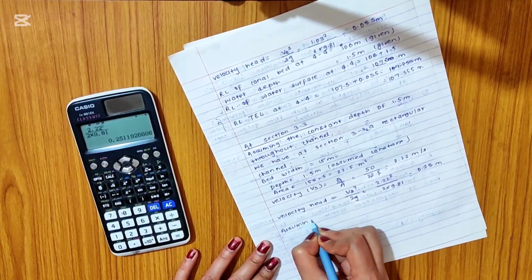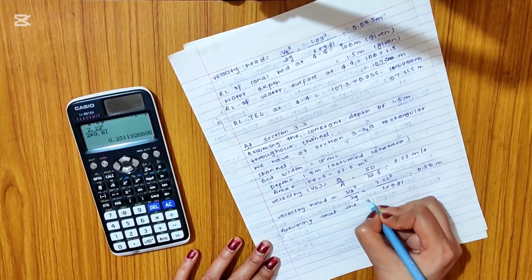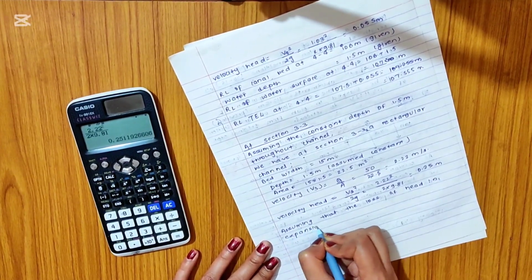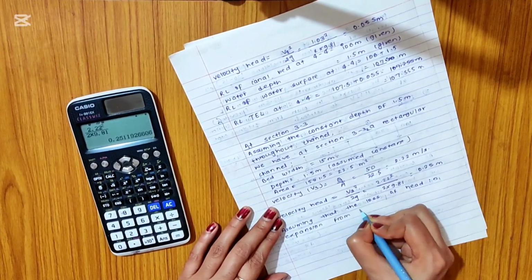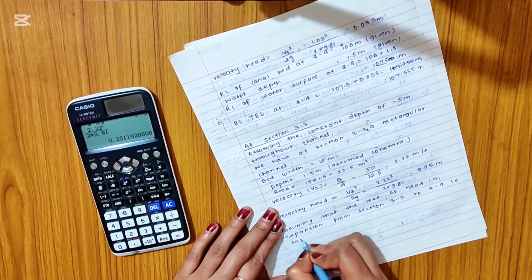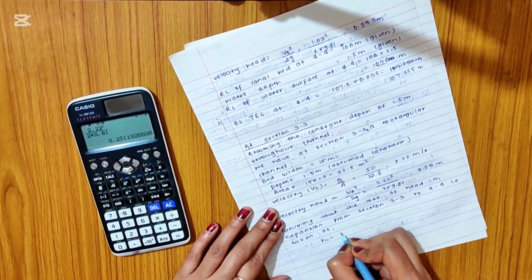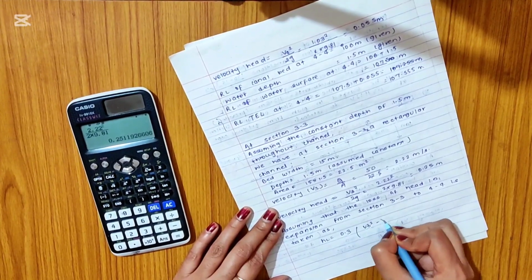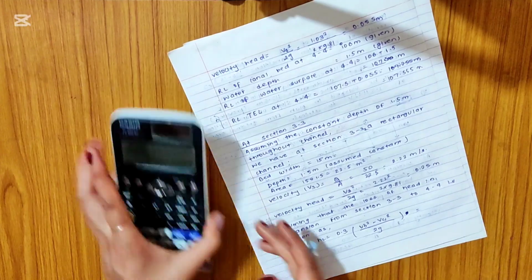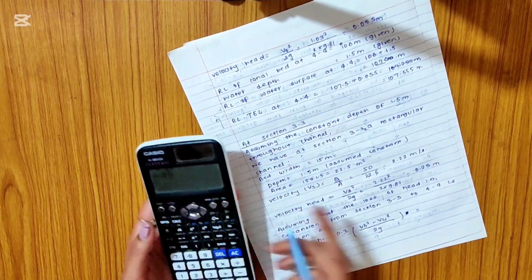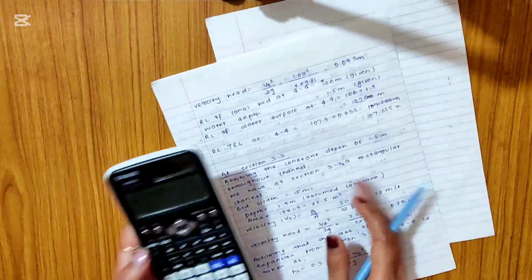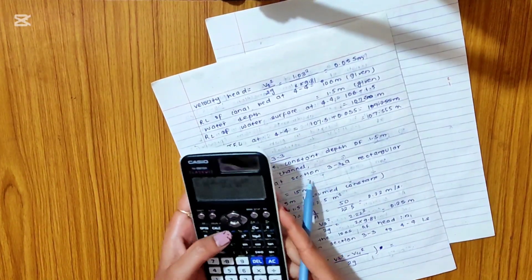Now assuming the loss of head in expansion from section 3 to 4 is taken as HL equal to 0.3 times (V3 square minus V4 square) divided by 2g, which is 0.3 times (2.22 square minus V4, which we calculated as 1.03, square) divided by 2 into 9.81, which is equal to